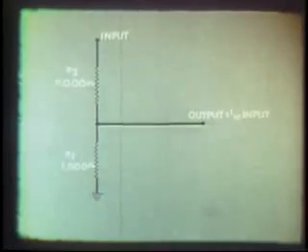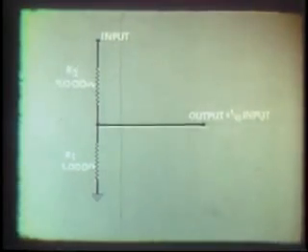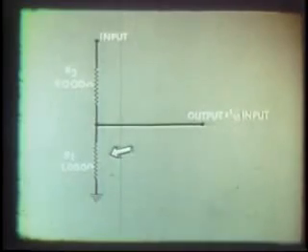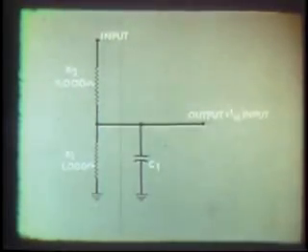This divider usually will feed into a circuit of some kind, like the input of a vacuum tube. As a result, some capacitance is bound to appear across R1. This capacitance would be in the form of stray wiring capacitance and the input capacitance of the tube. We will represent this capacitance by adding C1 to the circuit.